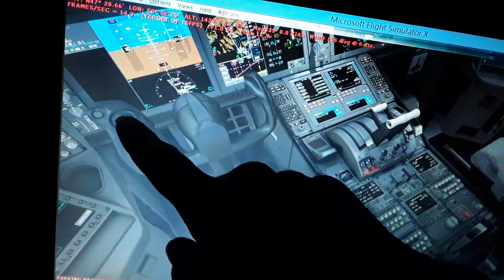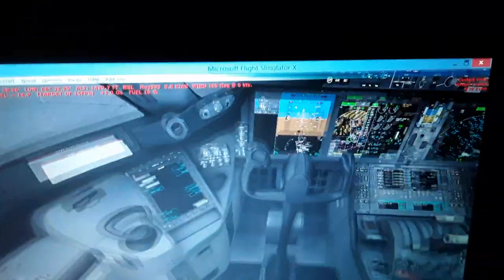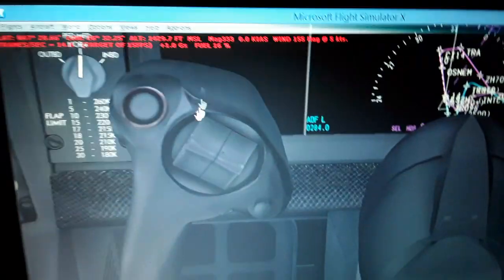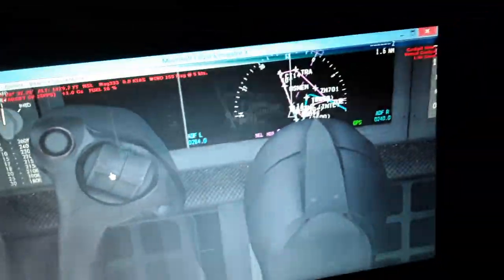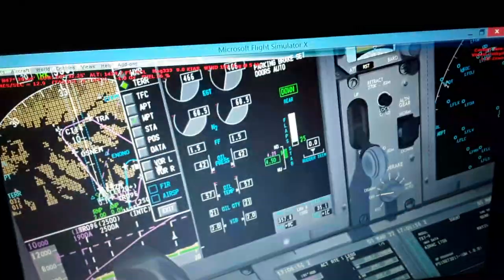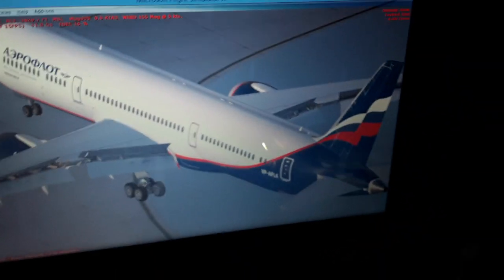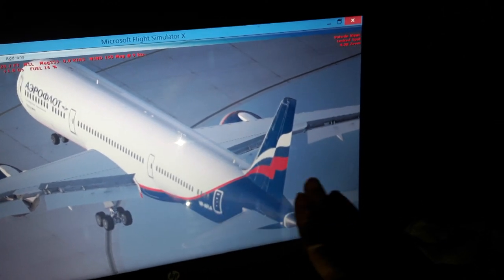So I told you we have the horizontal trim stabilizer here, this switch. So you trim down the aircraft. Over here you see the horizontal trim stabilizer, here the position, and this will make the tail going up or down in flight, both tail surfaces, left and right.